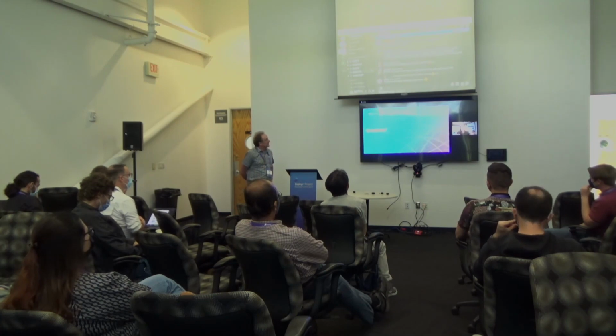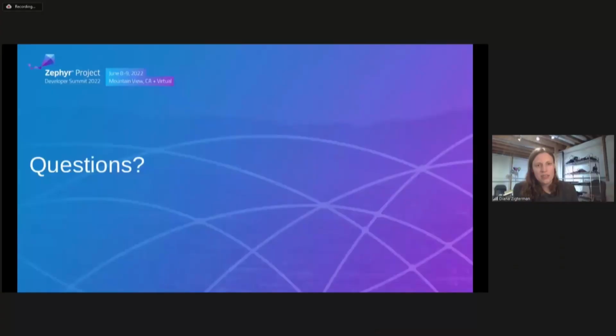So the external TCPCs are pretty much always I2C. Usually you'll want to run them at least at 400 kilohertz to get a good response time out of your system. And then the internal TCPCs usually use just a specified set of registers. So if you're on an STM chip or an ITE chip, there'll usually just be a set of registers you use to grab out your TCPC information.